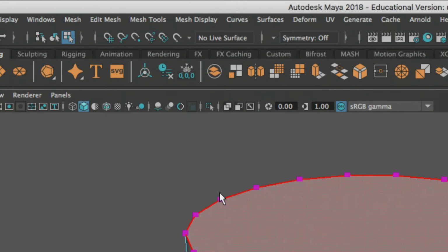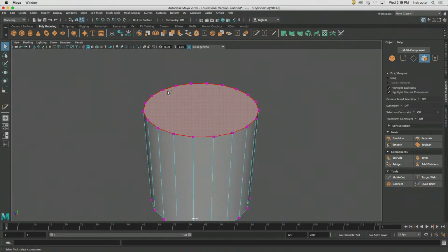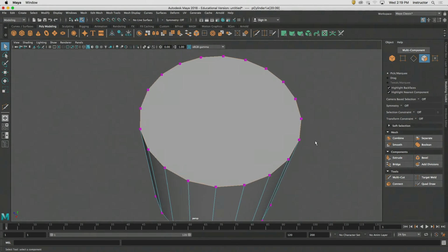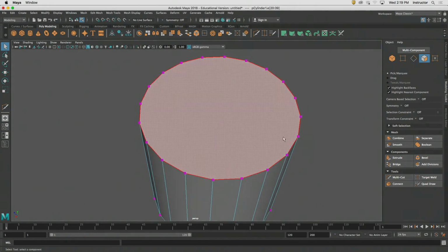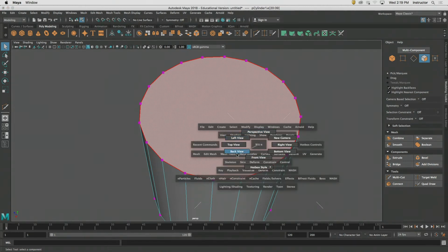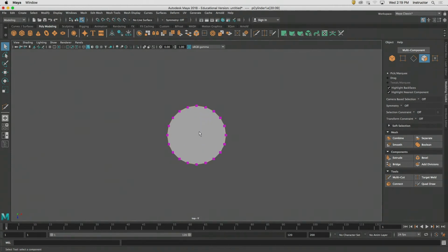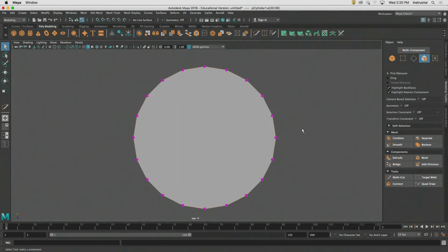Okay. So fill hole is a great way to fill your hole and to close some stuff up pretty quickly, okay? Now, there are a zillion different ways that we can go about doing this. This is just a way. But now we have a surface that we can very easily continue to go in and slice and get into quad polygons, okay? So I'm going to zip over into the top view here real fast. And we'll get to work, okay? Multi-cut's a great tool. It allows us to very quickly connect the dots, okay, like that.